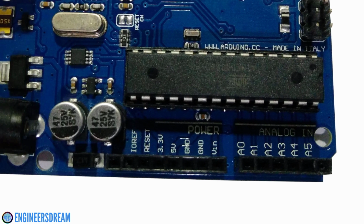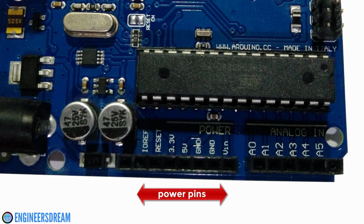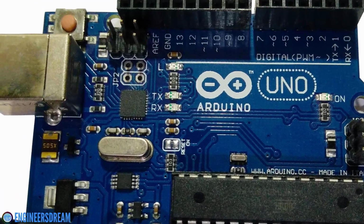Neighboring to the analog pins, we have the power pins. Now, using the power pins, we can supply power to the sensors and other electronic components that run at 3.3 volts and 5 volts. So, as you can see, there is one 3.3 volt pin and one 5 volt pin for supply. The Arduino consists of 3 ground pins, 2 pins at the bottom and 1 pin at the top.